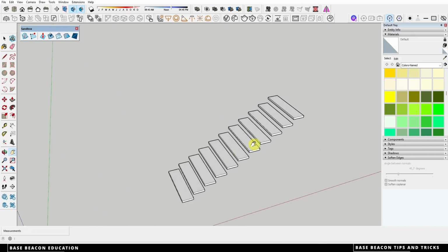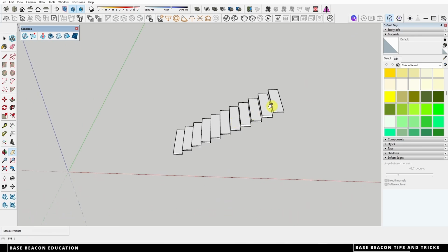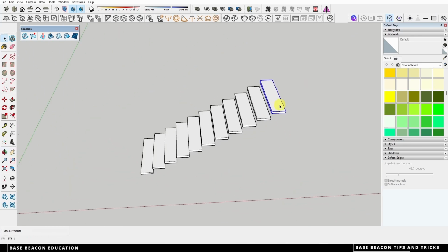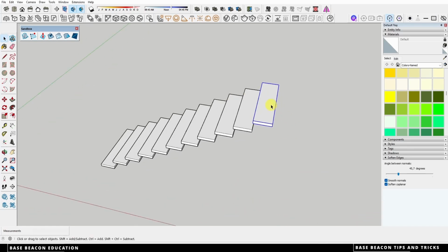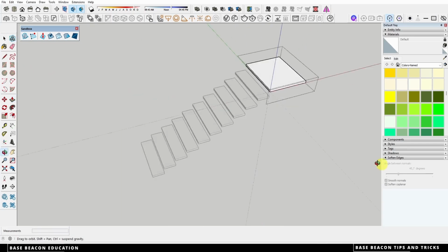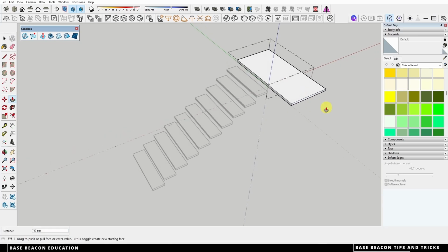Now we have our staircase, and then I just wanted to turn and go the other way up, like a dog leg type staircase. So with this one, that's 300, I'm going to add 700 to make it a meter wide, and then pull this again so we're going to have a 50 millimeter gap. It was 1.2, so it's going to be 1.250.